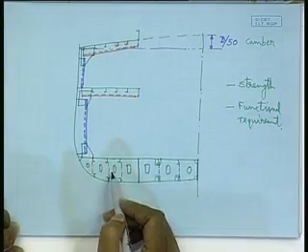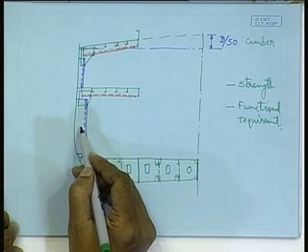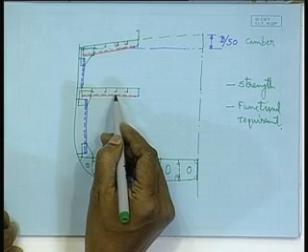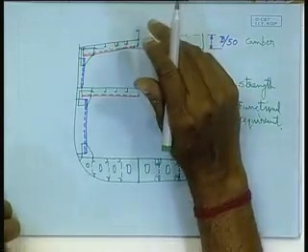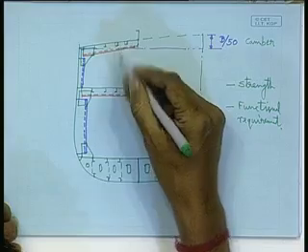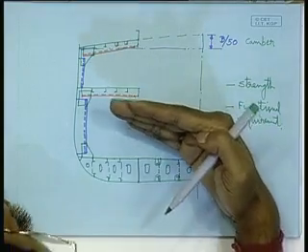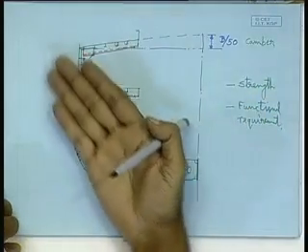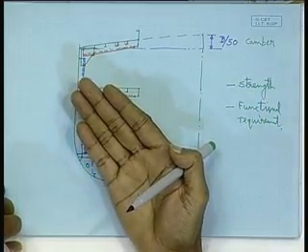What? We have the plate floor, we have the side shell frame, we have the deck transverse, right. So, this deck transverse and plate floors are providing support to the longitudinals as well as providing transverse strength in the transverse plane, isn't it? They are providing for the transverse strength.